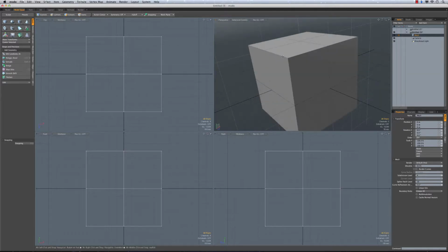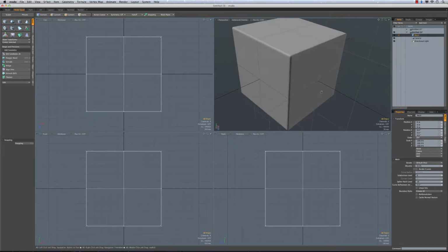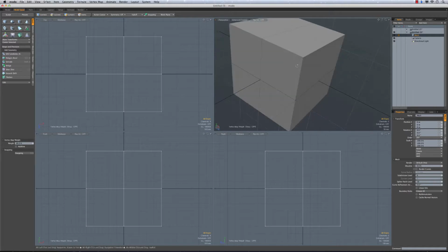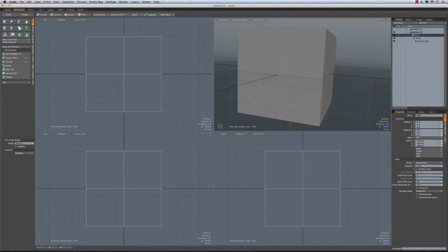So if you're looking at completely sharp edges here, this is going to be great. If you're looking at slightly rounded edges at a high subdivision level, also will work very well here. So if, for example, I step up to, let's go to level 6, and I'm just going to sharpen everything at the moment here. So let's just pull everything up to 60%, so we have a nice sharp edge here. This is going to work very well, and the benefit of working with something like this is that this makes a wonderful platform for sculpting.